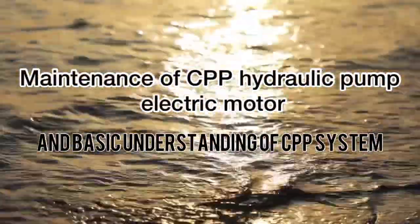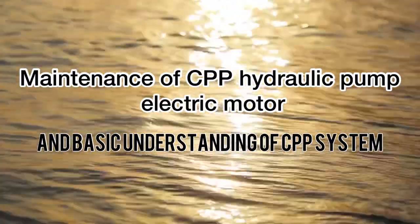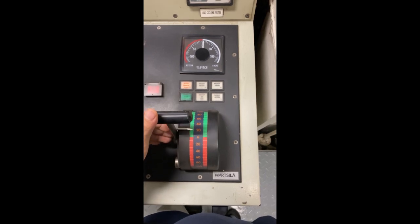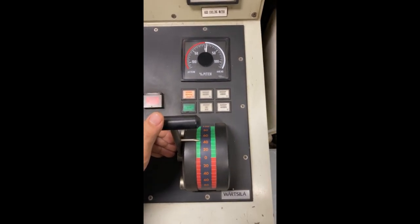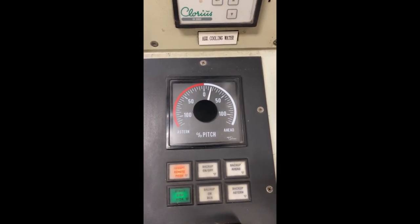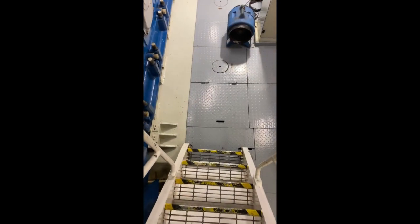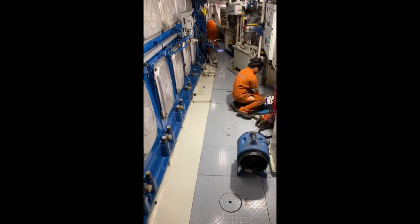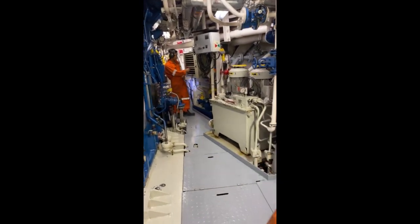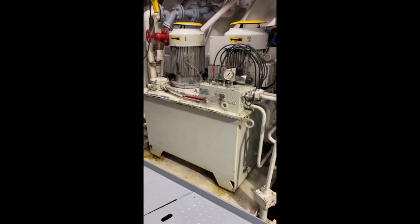In this video, I will show you how to do maintenance of CPP hydraulic pump electric motor and basic understanding of CPP system. This is pitch lever controller with pitch indicator. This is responsible for your movement, whether to go forward or astern for the ship. Here I show you the location of the hydraulic pump and hydraulic power pack unit.